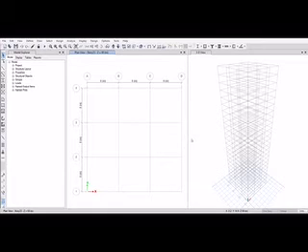Click on modify shear or reinforced bar. Change the design type to M3 only. Change the longitudinal bar to HYSD 500 and confinement bar to mild 250. And provide the cover to the longitudinal rebar group centroid as 25 mm. Both bars to bottom and click on OK.